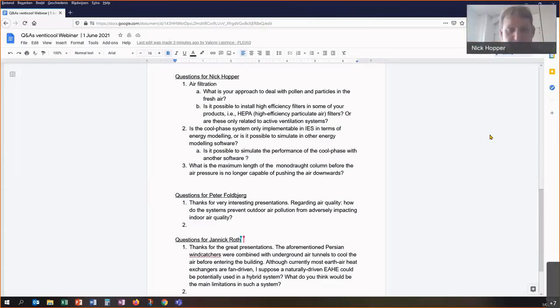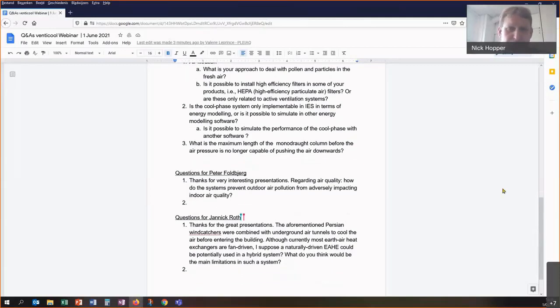Yeah, so that's all dependent on size, and then you get to a balance point of the size of shaft compared to the ventilation performance. Roughly speaking, 3 floors of a chimney effect. You then go into a balance that if you've got low level openings, the system acts more in a chimney effect than it does on a top down ventilation, dependent on wind scenario. But again, dynamic simulation can model all of that, and it can take that into account on low level openings when they're utilized, as well as the wind effect on top down ventilation.